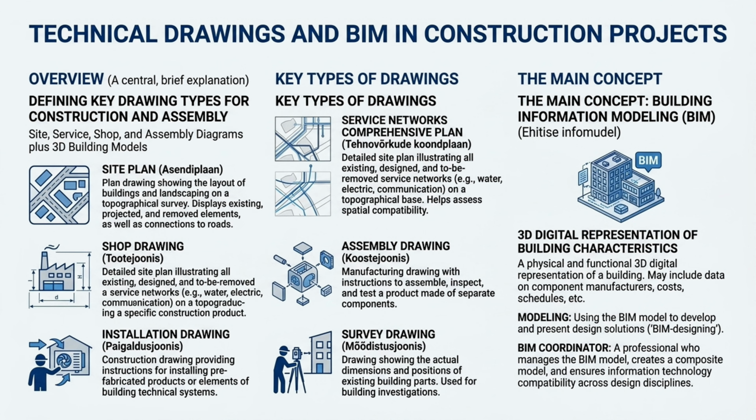Installation drawings or paigaldusjoonis are used for the actual construction work on site. They contain step-by-step instructions for installing prefabricated products or building systems, ensuring everything is placed and connected as intended. This may also be called a montage drawing.